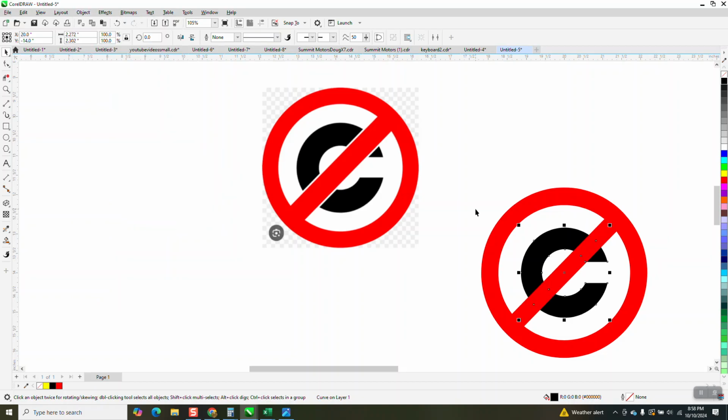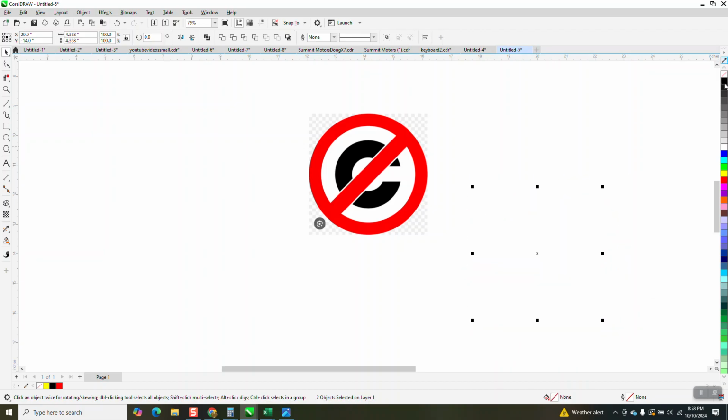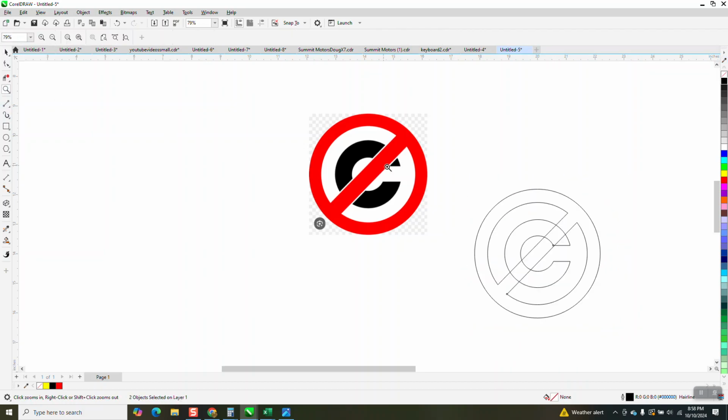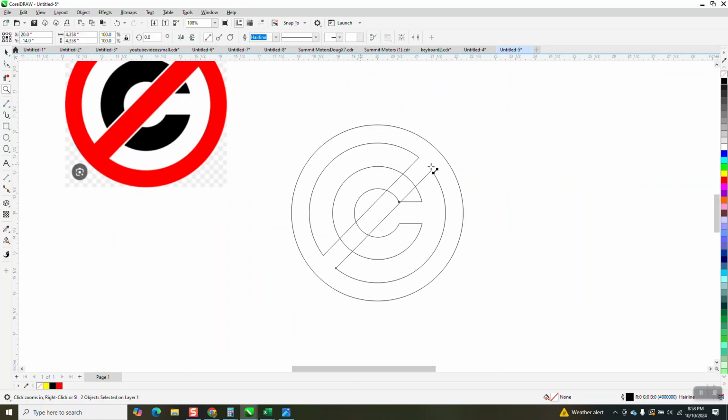Now, that's part of his question. The other part was how would you get this line? There's two ways to do it. Probably the easiest is to left click, right click. And we could do it several different ways, but let's just take a 2-point line and let's rotate it a negative 45 degrees. And let's put it right on that line.